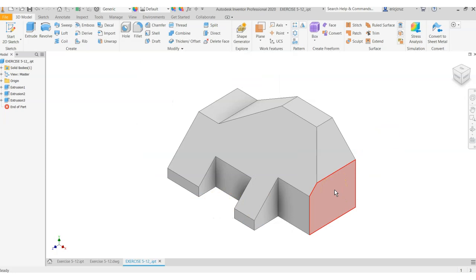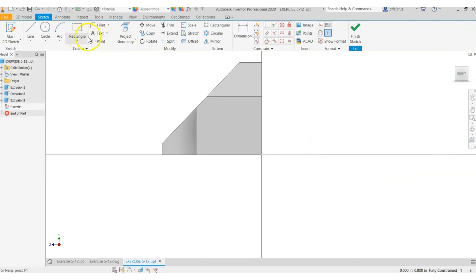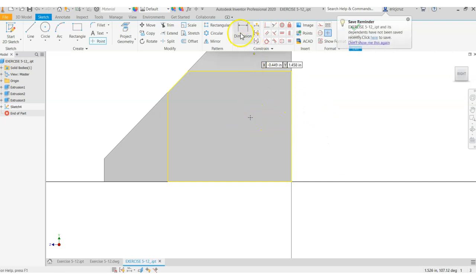And then on this right side, right click, new sketch. And we're gonna use the point to make a hole. So click point. Actually, project geometry first, then click point. Okay, don't let your point snap to any of these lines. I don't know if you can see it on your screen, but there's these little dotted lines that pop up. Don't let it snap to that. Find a spot where there's no other extra lines and then click one time for your point to get set in there.